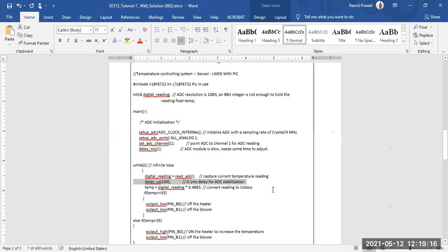You guys will be doing this in your projects as well. Those of you who are using the temperature sensor, those who are using the motors, and those people who are also using the ultrasonic sensor. All of you are going to be using sensors definitely, right? So you'll need to calibrate it. So in this particular case, you take a reading from the digital sensor, we need to calibrate it. So this is what is being done here, so that the values are converted to a sensible form.